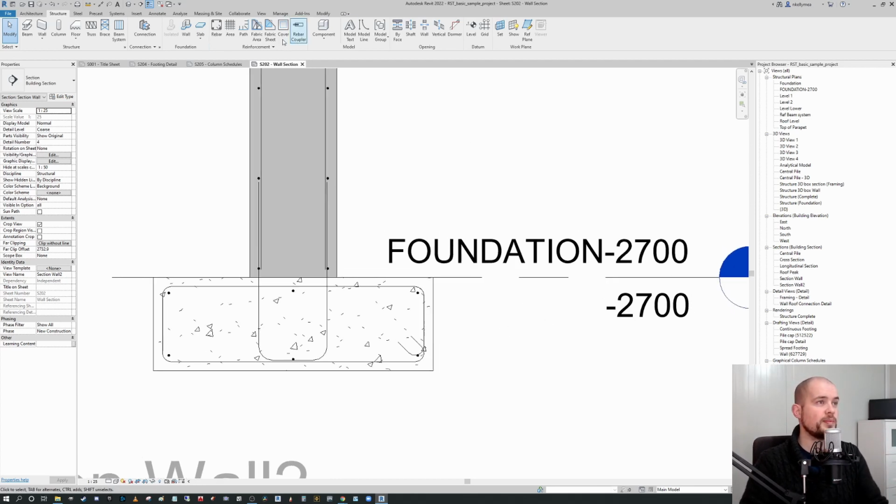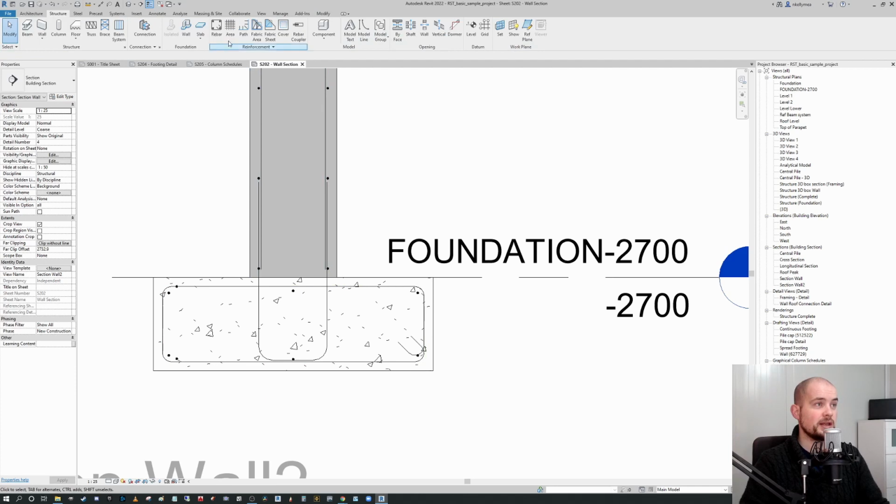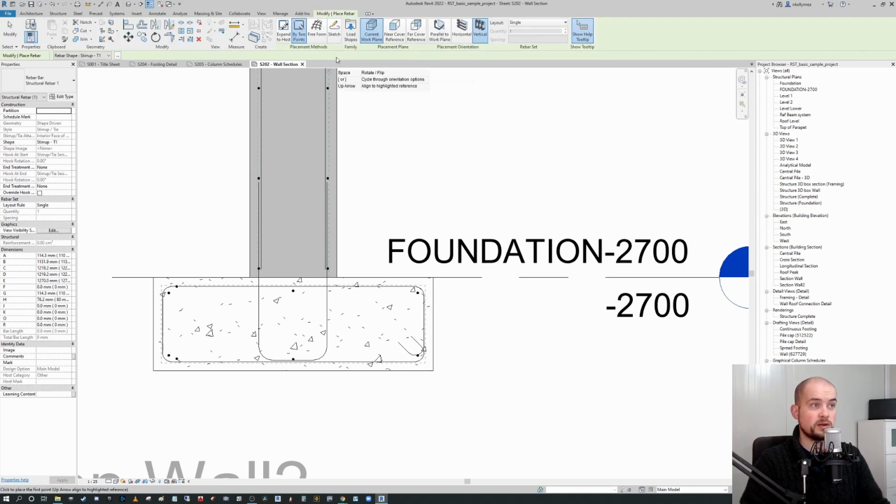So let's say I go back to rebar here and I want to do 2 points, but I want to do it in the vertical in the opposite direction. So let's say I draw a vertical in the opposite direction. That's a 2-point rectangle that's been drawn in the vertical plane perpendicular to the one that I've done. And I cancel that, and then I go back into my rebar tool. It's going to remember the exact settings I had previously. It's going to remember it by 2 points.